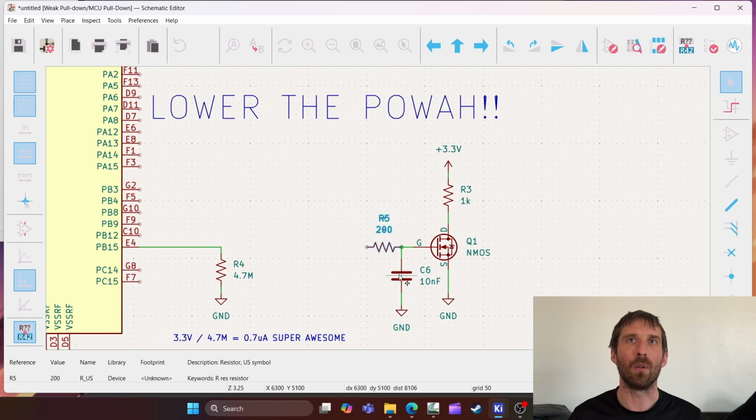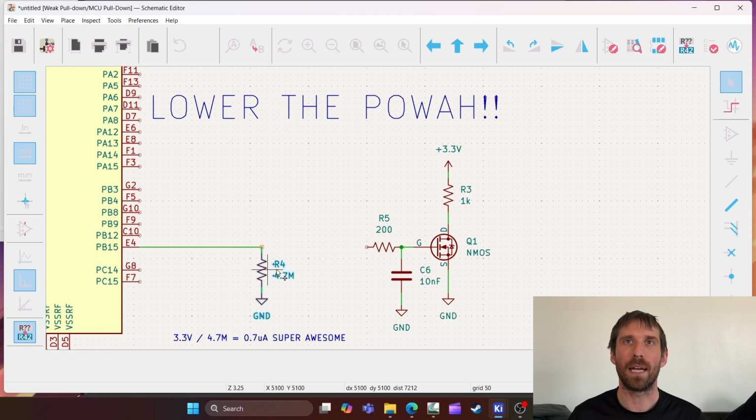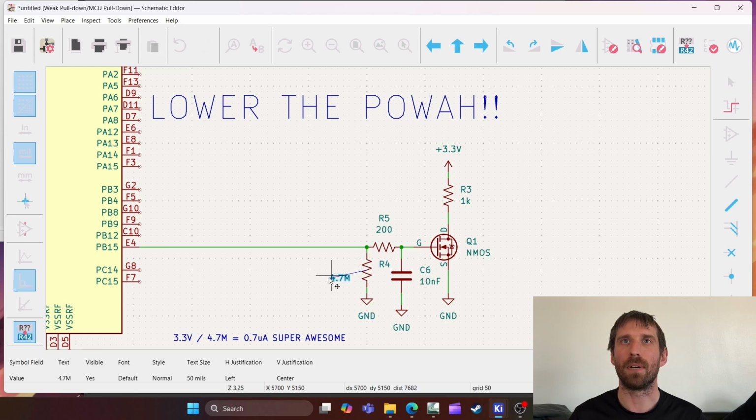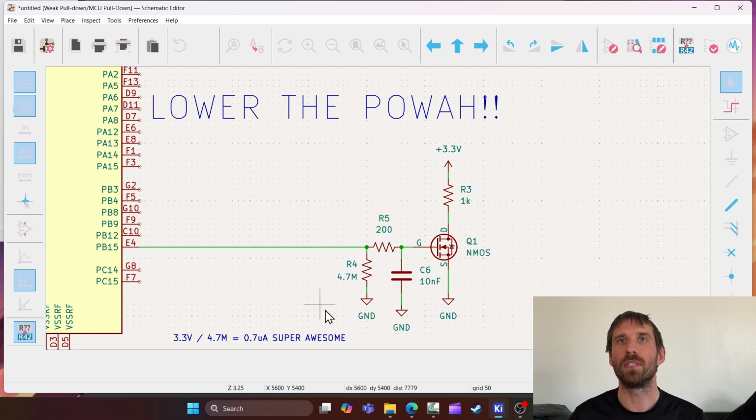So this is going to form a low-pass filter right here. Another thing we've got to do is, in the layout, we need to have all these close. So we're going to put it nearby. This is a hint to myself, or to somebody else doing a layout, that all this needs to be close, because you've got potentially a crap ton of inductance on this.